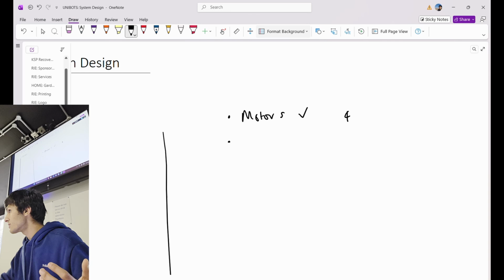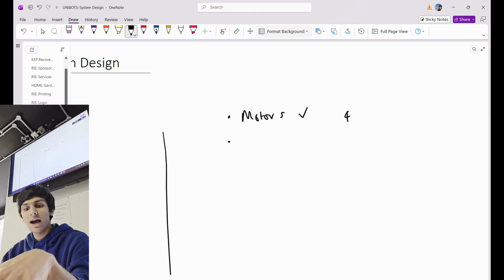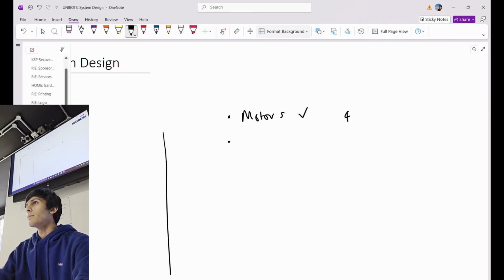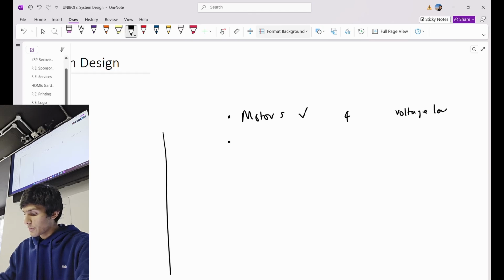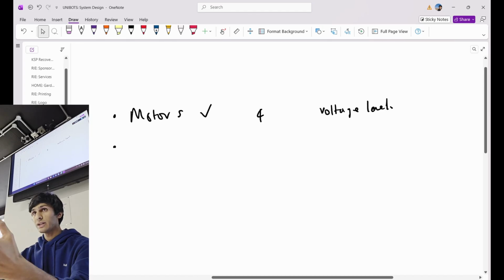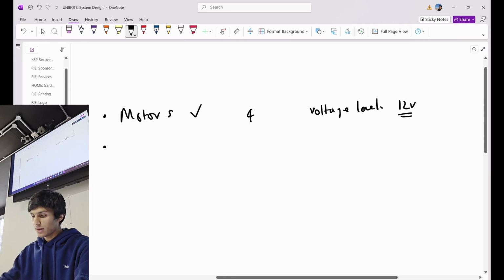So when you have motors, you need to pick. We've got a lot of motors in our cabinet already that you can pick from, but you could also see if you've got the budget to go buy some more, and you can look up whether they're brushed or brushless. You can look at whether they've got encoders or not. Lots of choice, but you want to make sure that you understand what the voltage level of these are, because the voltage level of motors is important for making our whole system work together as a complete unit. The ones we have in that cupboard are 12 volts. A lot of them are 12 volts, but some are 6, some are 5, some are 24. Basically, this is a number that will matter when you start to wire electronics together.